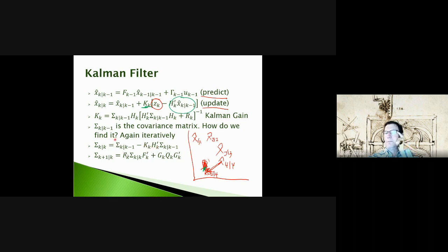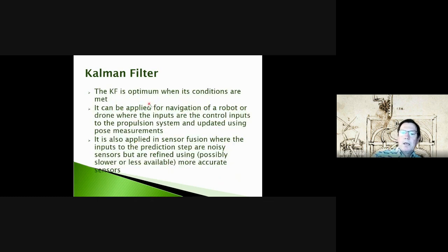And so we can take the prior estimate and again transform it using this transformation there, and using our estimate of our Kalman gain, and then update it based upon our measurements, right? And this is the amount of noise we have in our measurements. So, all right, there's a lot to unpack there.